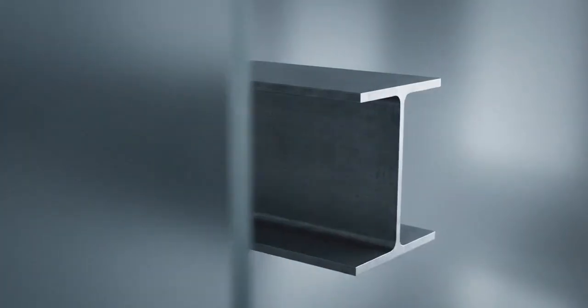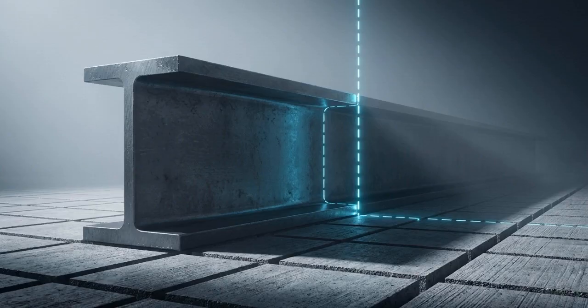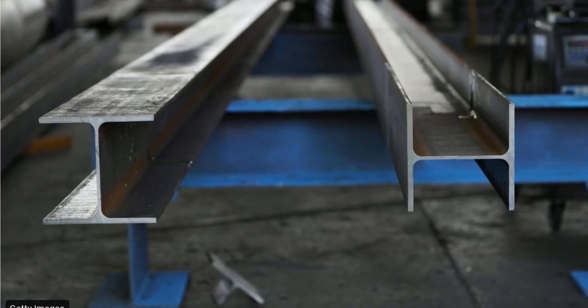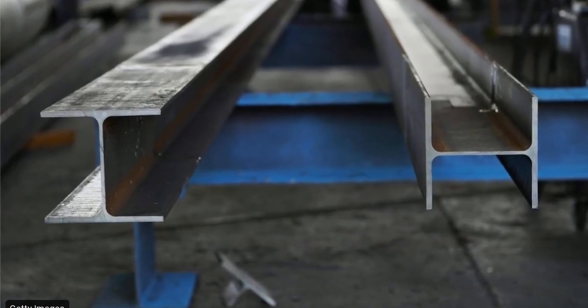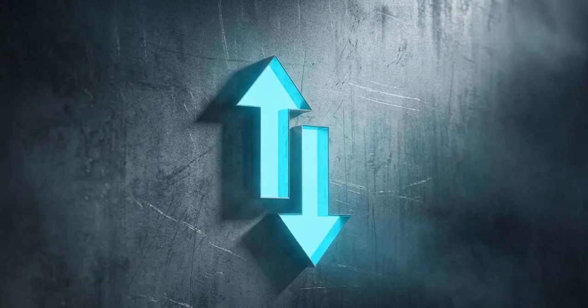To calculate those internal forces, we have to zoom out of the macro environment and drop directly into the microstructure of the steel itself. Engineers analyze this space using a technique called the method of sections. They mathematically slice the structure open with an imaginary plane to expose the internal pressures hiding inside. This theoretical cut reveals the naked interior of the structure, specifically the thick vertical web running down the center of a steel I-beam. Here we find the beam's primary defense, shear force.